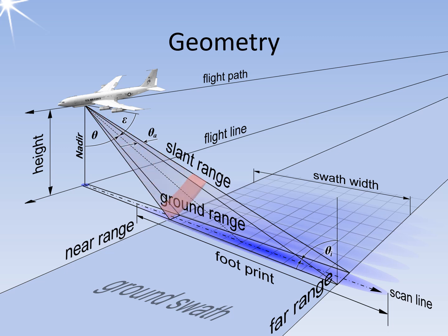The echo signals are stronger at closer ranges compared to farther ranges. However, at very large distances, the signals become significantly weaker, and the geometrically resolved ground elements, or pixels, increase in size. This leads to an upper limit on the possible scanning range. In the accompanying graphic, the pixels are intentionally depicted as larger than usual for clarity. In reality, their size is typically in the order of a few meters, with a swath width spanning several 10 kilometers. A line can contain several thousand pixels.